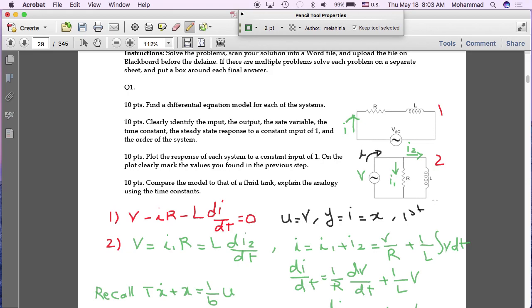And the current passing through the inductance element comes from the basic equation of the inductance. If you remember the basic equation of the inductance, I can write it up here. For an element L, the basic equation is V equals L di over dt. That's the basic equation. Now, what we are trying to find is the current, which means we have to take the basic equation and do what to it? Integrate it. So you need to integrate it.